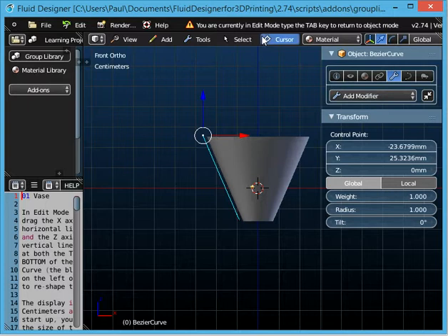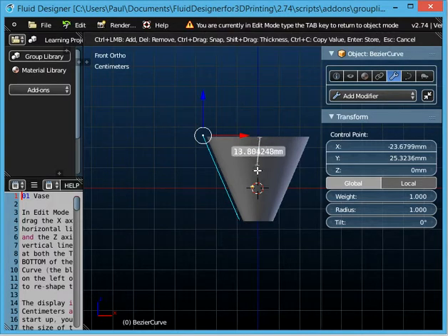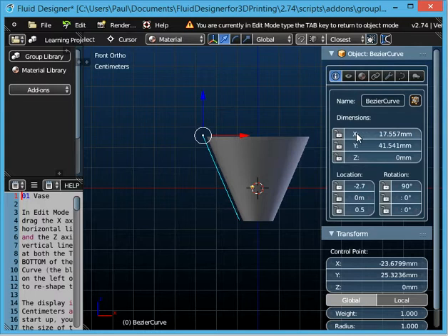If you want to measure it more accurately, if we look at the end of the toolbar here, there's an interactive ruler. So we can measure the height of this object, which is 41 millimeters. That's an alternative way of looking at the height of it. But also in the properties window here, if we click on the information icon, that's the first icon here, we'll see what the X, Y and Z dimensions of this particular object are.